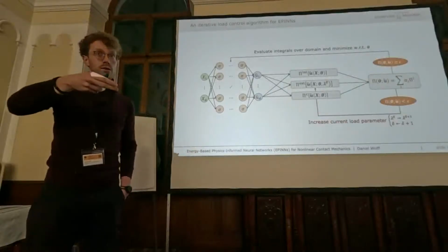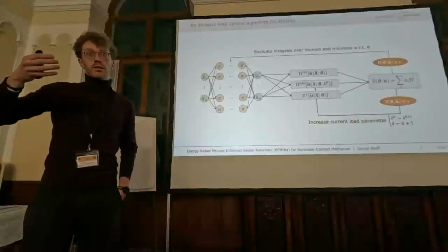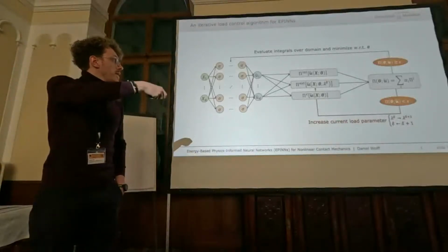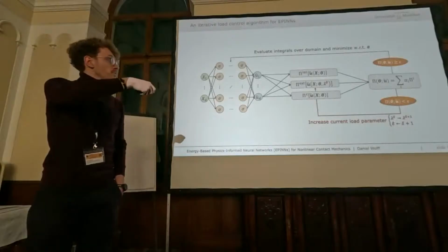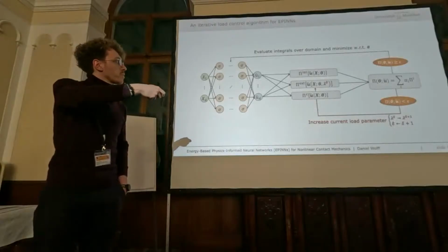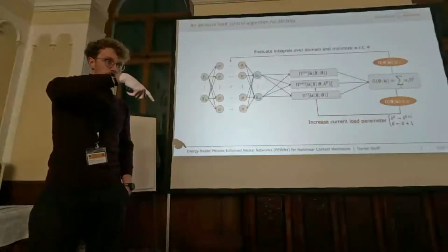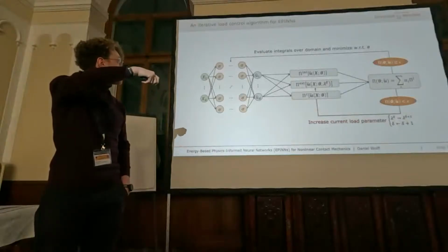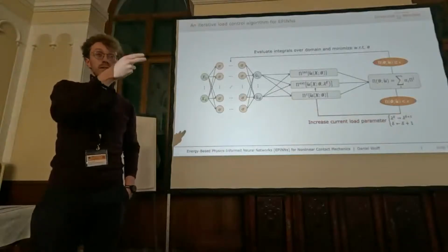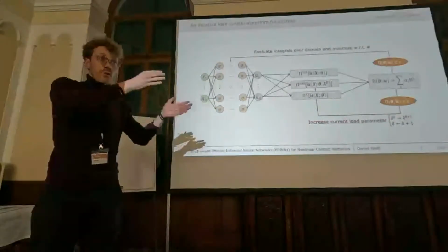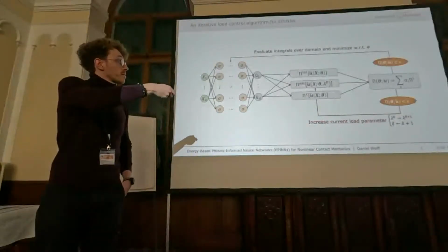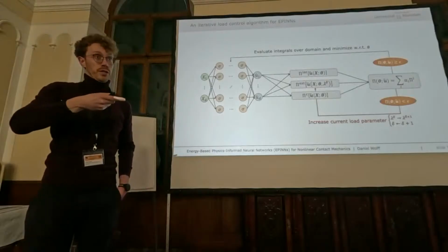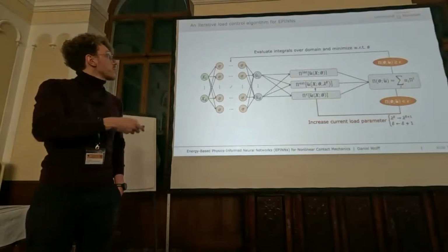So we go to the next load step, same as you would do in classical FEM. We increment our load step counter, and we again start. Now the important part is that we continue training, yes, but we do not start from zero. So we do not start with a randomly initialized neural network, but we basically start also, as we do in FEM, from the solution that we got when this termination criterion was first fulfilled, okay? So this is the general idea.